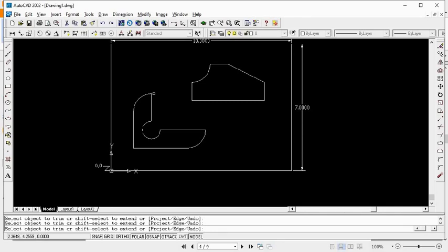Note, if a corner is rounding outside, then we can fillet it, but if it is rounding on the inside, then we cannot fillet it. What we do there is you just draw a circle and you trim that circle. So here, if I were to come and now dimension whatever I have here, you can be sure I'm going to get exactly what is given.